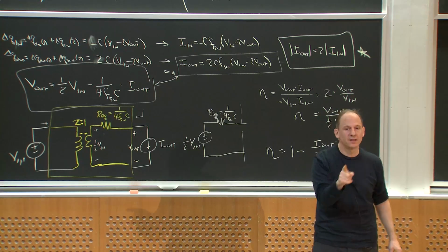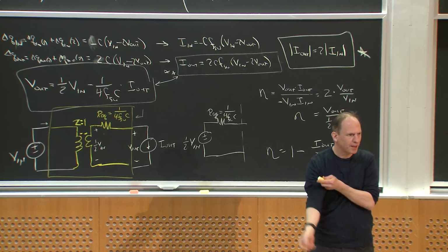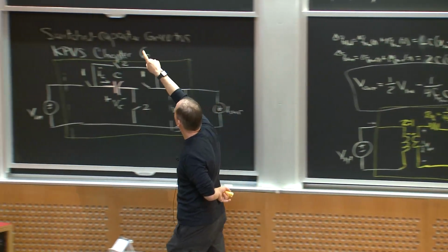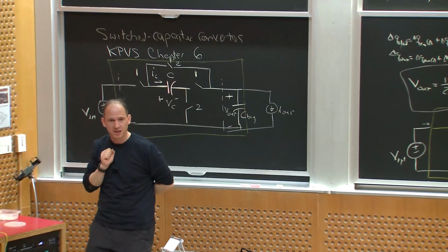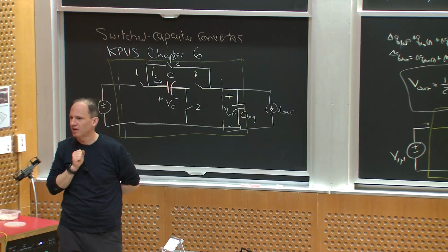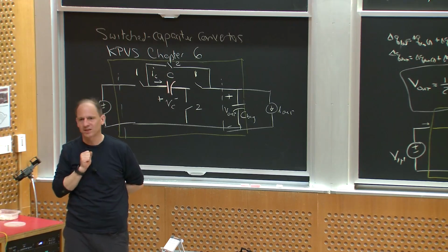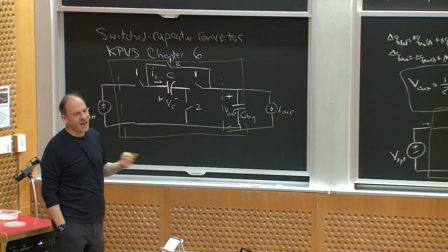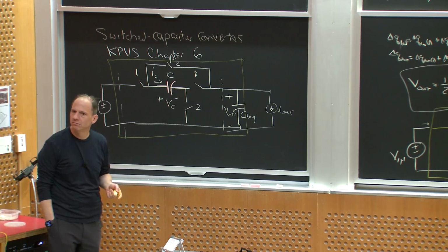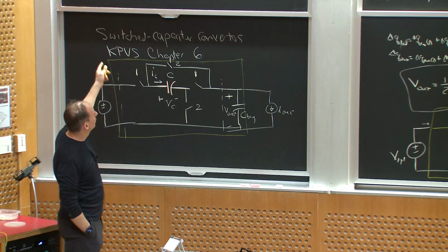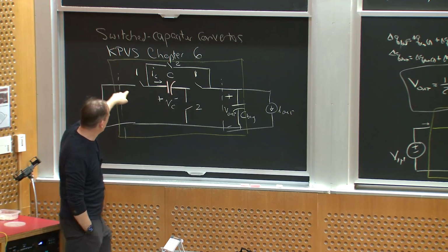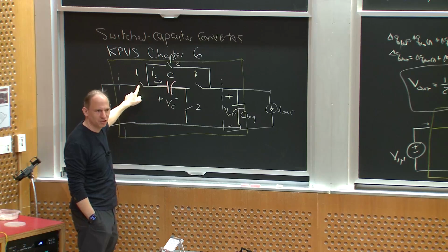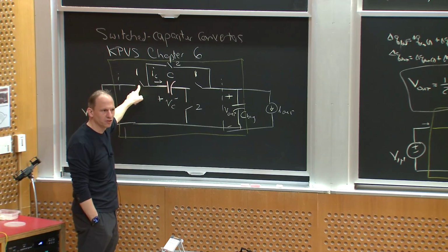Now, when I'm saying this, what losses am I counting when I'm calculating this efficiency? The losses I'm counting are essentially the resistor loss, the losses in the switch resistances and any parasitics in the capacitor. It's what we would call capacitor charging loss, right? I'm not counting, like, if these switches have gate drives and the gate capacitance I charge and discharge, or other losses like that that are internal to the switches.